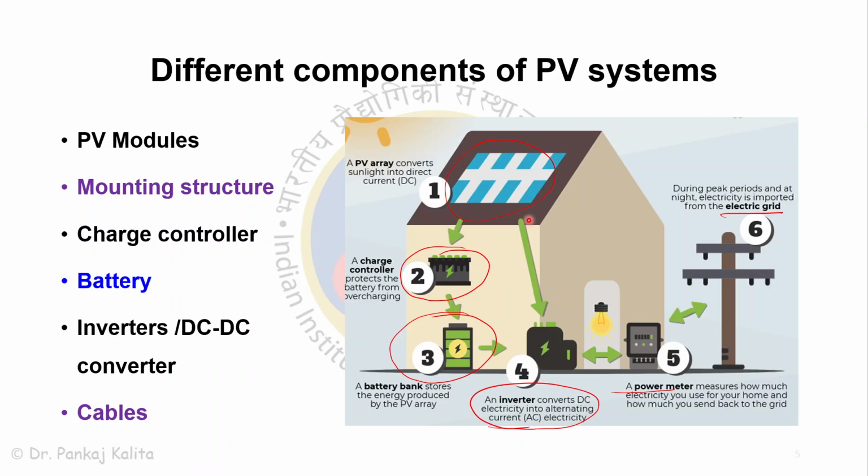You are aware that with the variation of the angle, the power received varies. So they are slanted to make use of most of the sunlight, so that it is perpendicular and covers the maximum area of the solar PV.